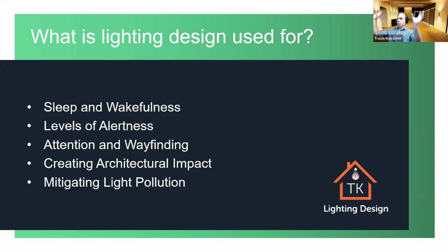So it's not just big bulbs right in the middle, big, super bright. I'm sure you've probably seen them, COBs, there's places for those. That's great. But like baffled, indirect light that's coming down, filling the space with voluminous light. That way you're not straining to see and you're not getting concentrated amounts of light in your peripheral vision, which causes glare and headaches. So it helps out a lot by having that foresight, picking out specific product and part numbers that help eliminate the glare and add adequate levels of lighting.